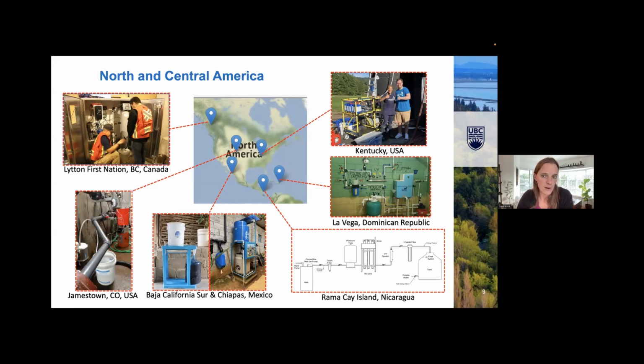They started with surface water from a creek and ran it through a series of 3 different filters, and then disinfected it with low pressure ultraviolet light. One of the challenges encountered was turbidity fluctuations, since it was a surface water source, from the annual snow melt.